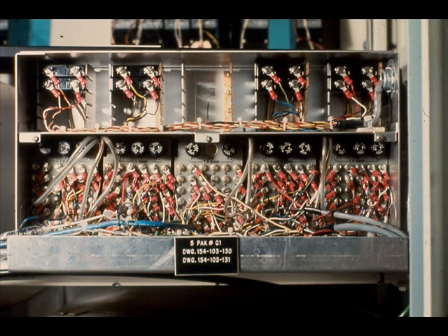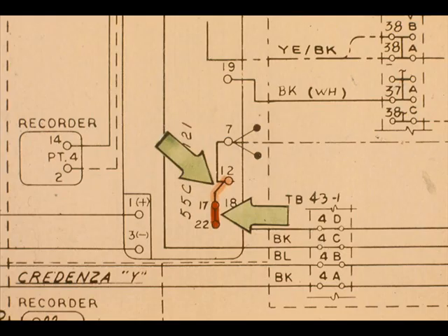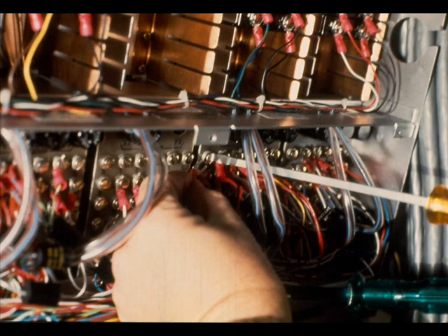Complete the remaining wiring. Always test the computer wiring for continuity before you terminate it. Make sure the jumpers on the back of the controller are in place. Mark all the wiring you have tested and completed. The loop is now complete. It is ready for checkout, synchronization, and commissioning.